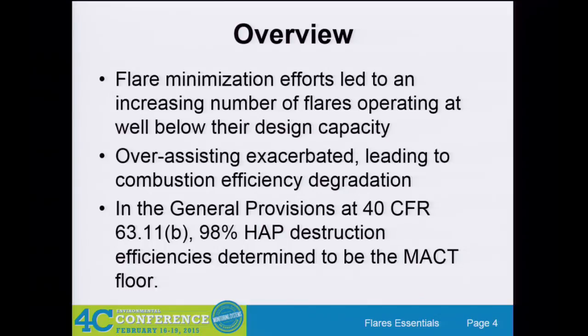And one of the things that we liked was this 98% HAP destruction is now the MACT floor. And this was kind of an interesting thing because, how do you set a MACT floor? I mean, you need to get, what I said, 10 to 11% of the industry following a certain set of control. Well, how did they do that? Well, they did it through enforcement. They got enough flares in a consent decree that got them instrumented in controlling their flares. They want to come out with a new rule, and voila, you have your new MACT floor.